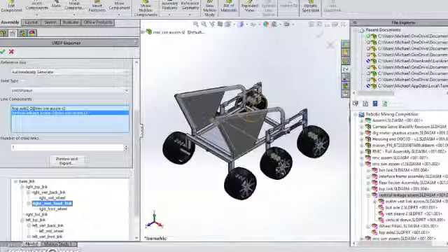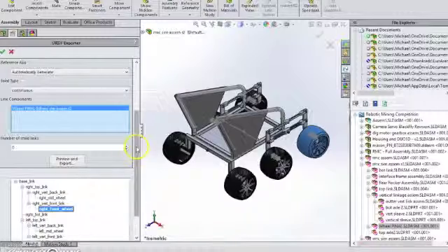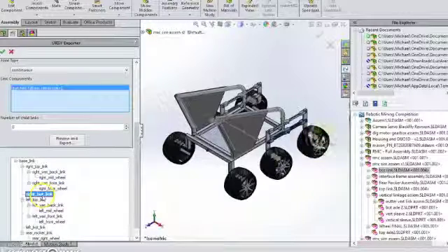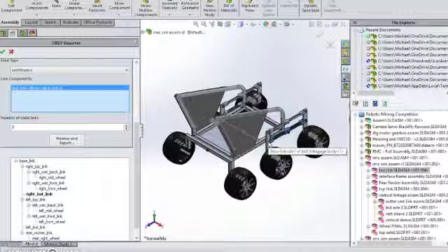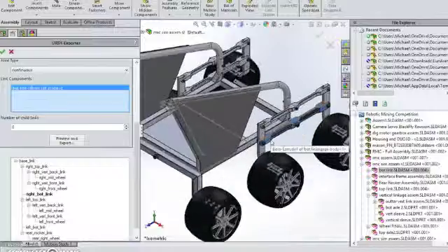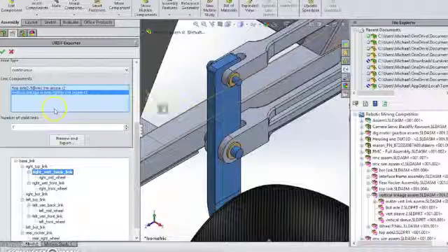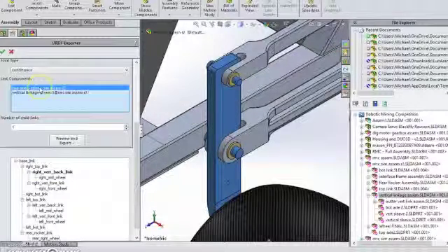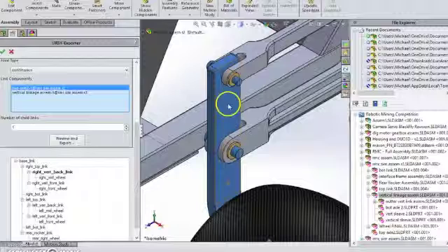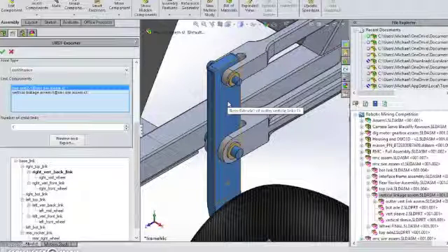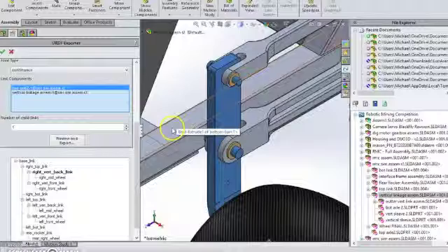Again, here we have a similar thing where we're building the tree structure downwards. And then we complete the series of open chains with the bottom link. Now, one thing that I sometimes find helpful in troubleshooting, because it can get somewhat tricky to get an export correctly, is sometimes it's hard to find these axes, so you can actually group multiple bodies into a link. So you see this vertical linkage includes an axle. Sometimes I include axles. I found that sometimes it helps the exporter go through, though that's purely anecdotal.